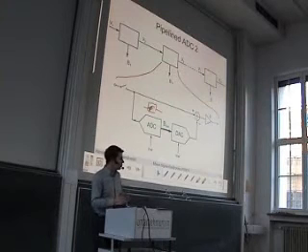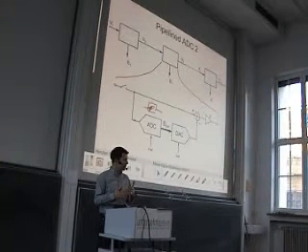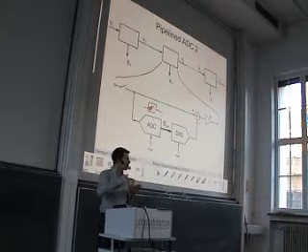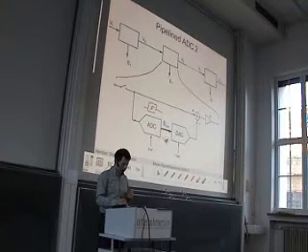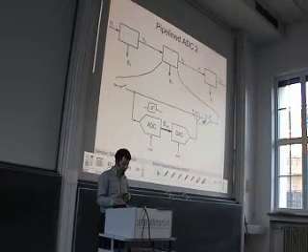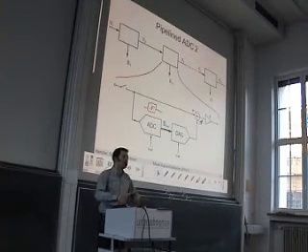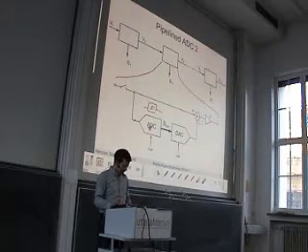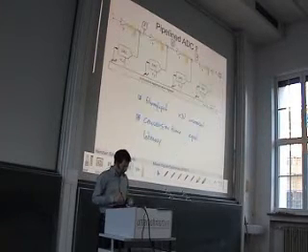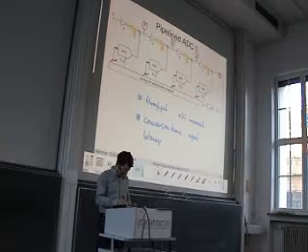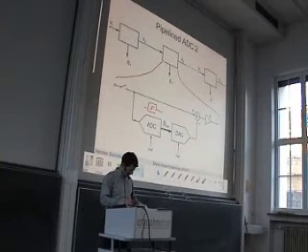Of course, we can do a multi-bit decision per cycle. So we could, for instance, subdivide the original interval in 4 sub-intervals. Then we have here a 2-bit ADC. And then we convert this result back and subtract it from the input, get here the quantization error and scale this back to the original voltage range. So this is more general. We can also use here a multi-bit quantizer. But for understanding, think to this picture. We can really assume that this is a single-bit quantizer for understanding of the basic principles.